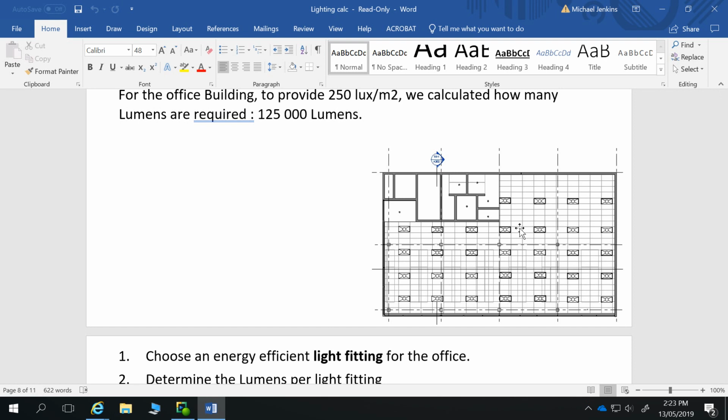If it was individual offices, of course, then it'd be different. It'd be designed differently for that. Within this reflected ceiling plan, we can see that there's a grid formation happening. So this is actually a fairly large floor plan for quite a large office. Those grids will typically be spaced at 1200 by 600 centres. And then each of these crosses with the circle in there, that's a lighting bay. So you'll want those spaced fairly evenly, and as you can see in this one, they're spaced at approximately every 3 meters, so that you get even light coverage throughout that room.